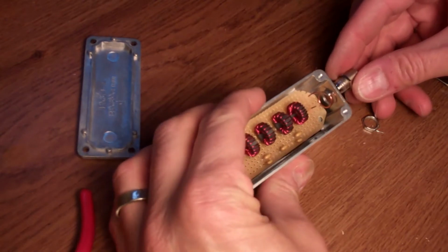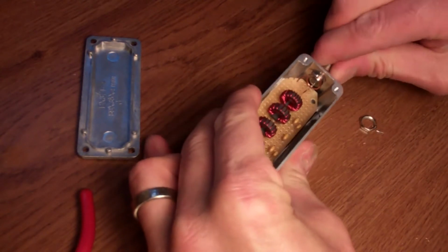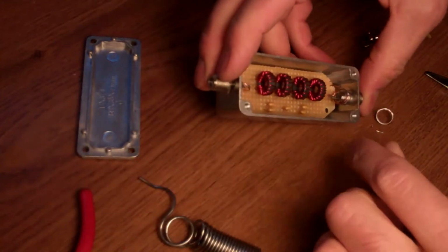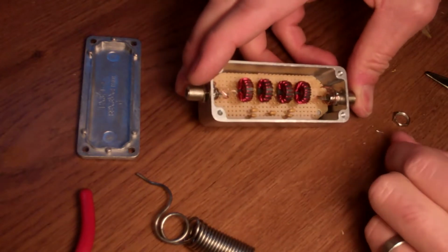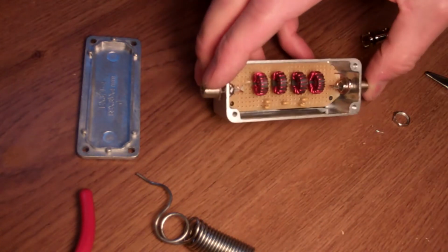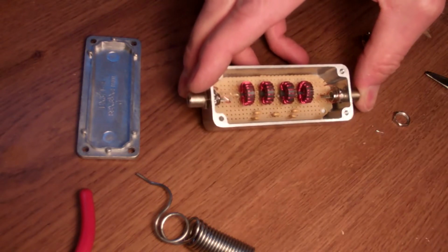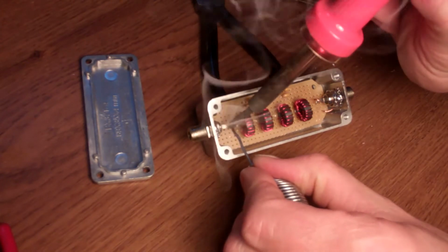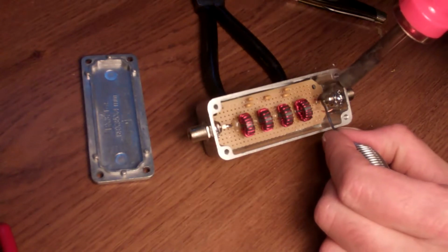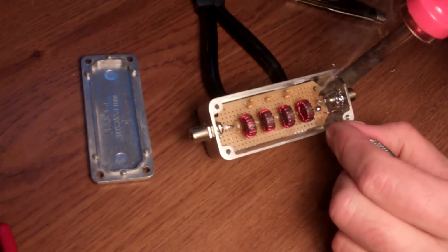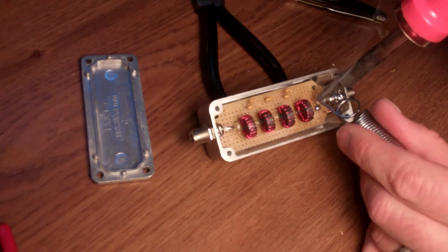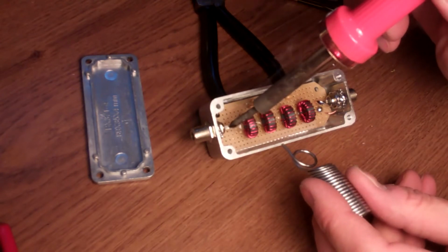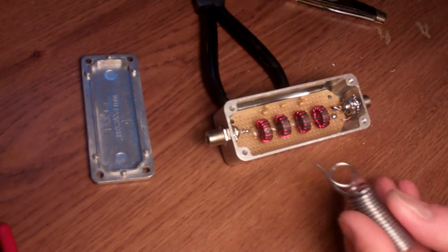Right, so now that the filter is seated within the box, I can proceed to put the F connectors in, and then I will seat the ground wire around the outside here, and I'll screw it up and solder the positive lead to the positive on the F connector. Lastly, I'm going to solder the center contacts to the positive of the filter input. So just put a little blob of solder there. Whoops, that's not good. We'll get that out later though. There we go. A little bit there. A little bit there. And we're done.